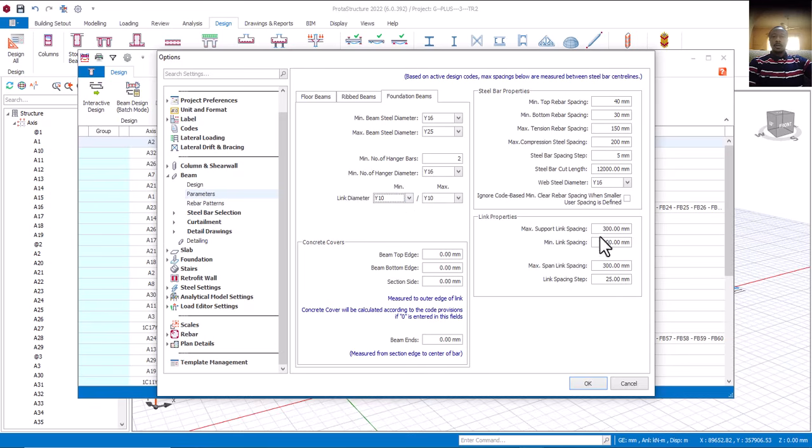Then come to this place now. This spacing, I'll make it 200. Is that okay? This one also 200. Then I'll come here now. Since it's foundation, I'll use 50. Normally you can use 35, 50, 35. Is that okay? But since we are talking about foundation, your cover should not be less. It should be what? 50, isn't it? Minimum should be 50. Is that clear?